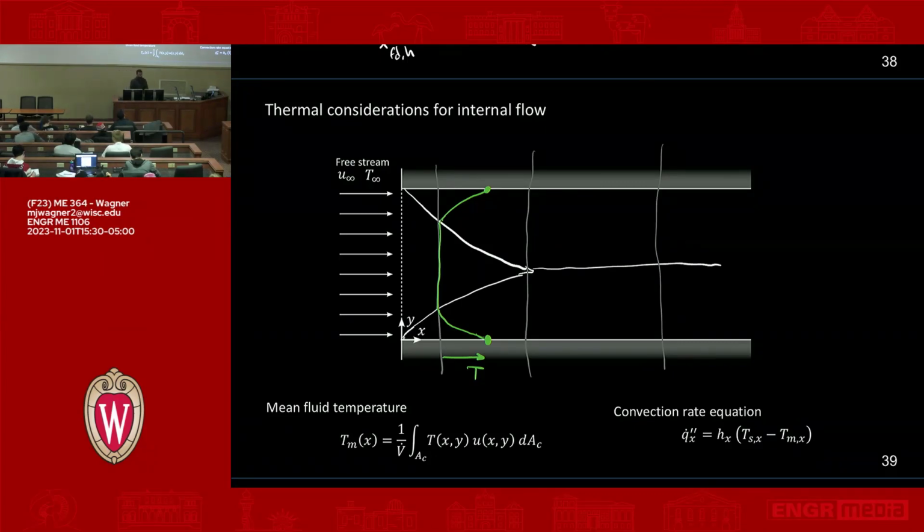Now as we get to the fully developed region thermally, that's just saying I'm still out here at TS, same temperature difference, but my profile is kind of established like this, right, where it's basically a parabola. So it's symmetric. The temperatures just meet at the middle. And then once that happens, then nothing changes, right? It's fully developed. So let's see. The velocity is fully developed.